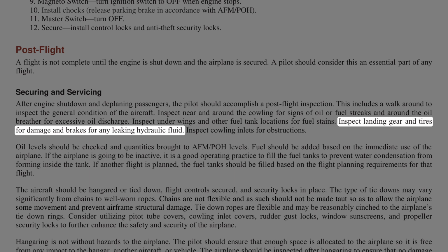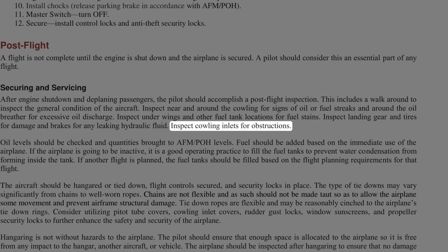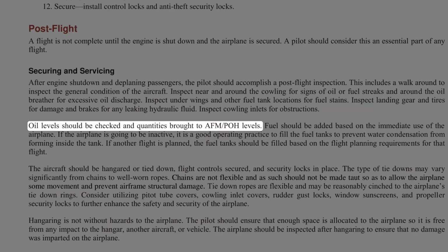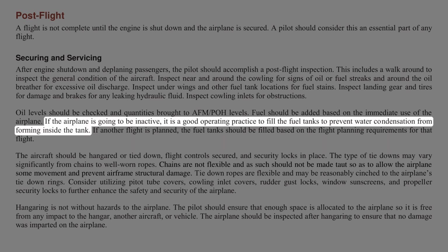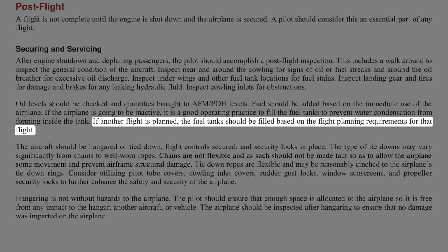Inspect landing gear and tires for damage and brakes for any leaking hydraulic fluid. Inspect cowling inlets for obstructions. Oil levels should be checked and quantities brought to AFM/POH levels. Fuel should be added based on the immediate use of the airplane. If the airplane is going to be inactive, it is a good operating practice to fill the fuel tanks to prevent water condensation from forming inside the tank. If another flight is planned, the fuel tanks should be filled based on the flight planning requirements for that flight.